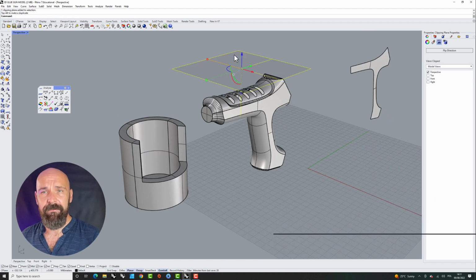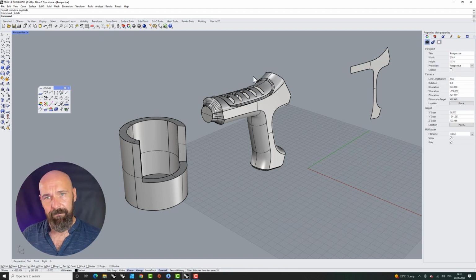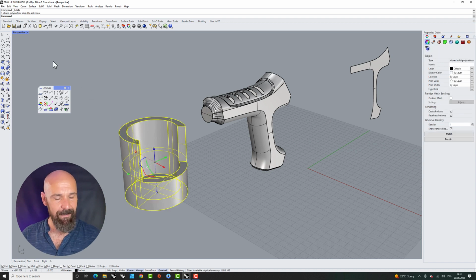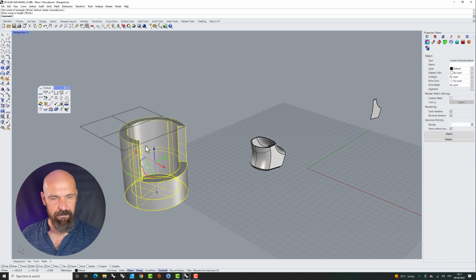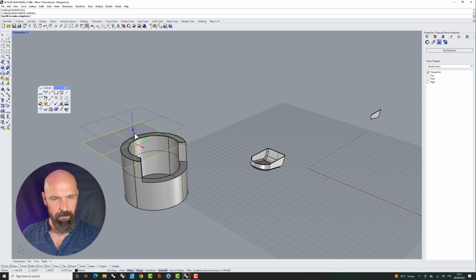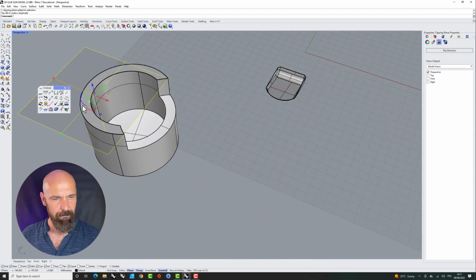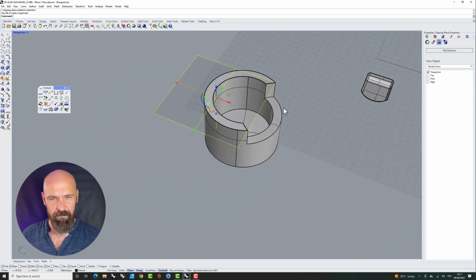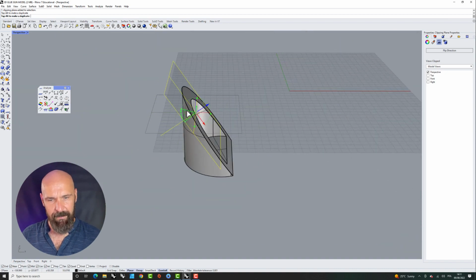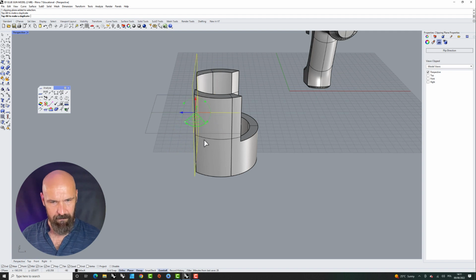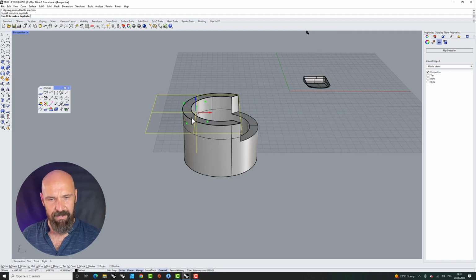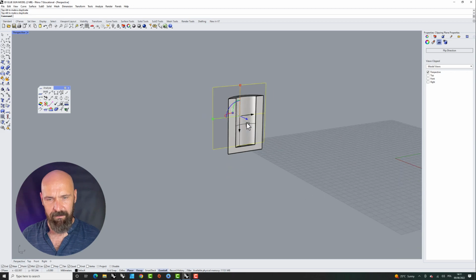Now I need to reactivate the clipping plane. I already deleted the one I applied to that object, and now I can apply it again to the new object, and this is where I want to cut it. And see, that plane is now inside as a box and has capped walls. I can rotate that clipping plane, and if you press shift you can just jump to 90 degrees and see it from another view.